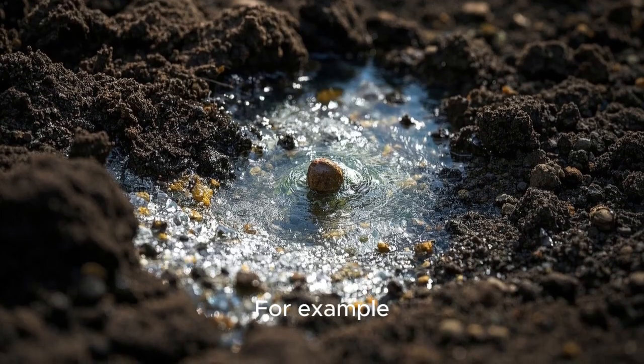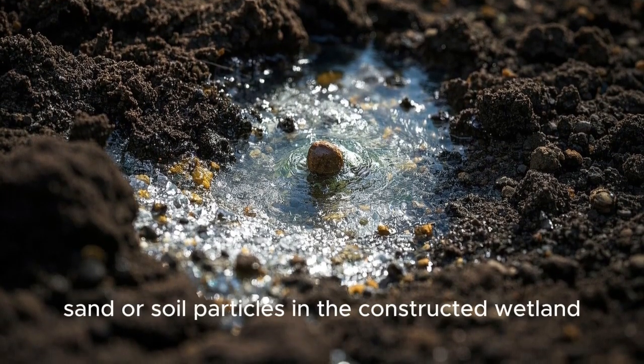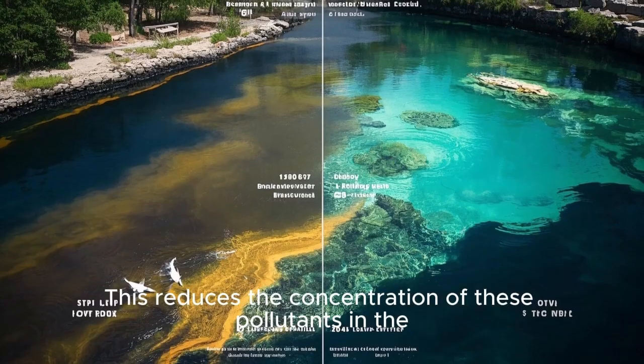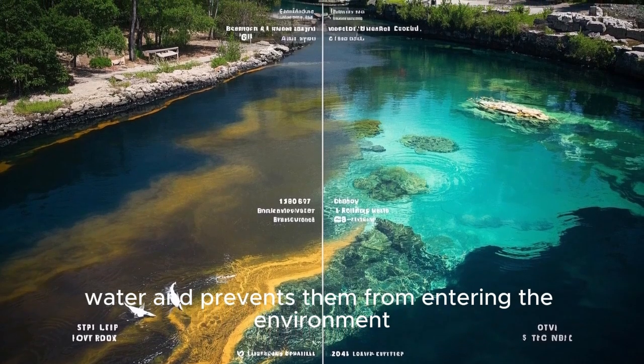For example, phosphorus and some heavy metals present in the wastewater can be adsorbed onto the surface of gravel, sand, or soil particles in the constructed wetland. This reduces the concentration of these pollutants in the water and prevents them from entering the environment.